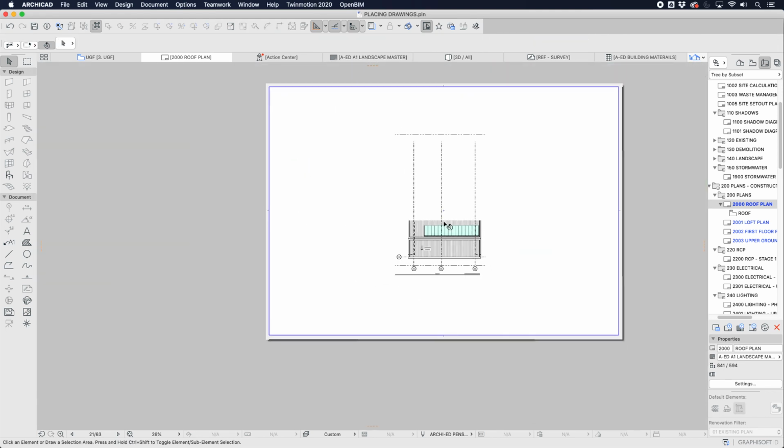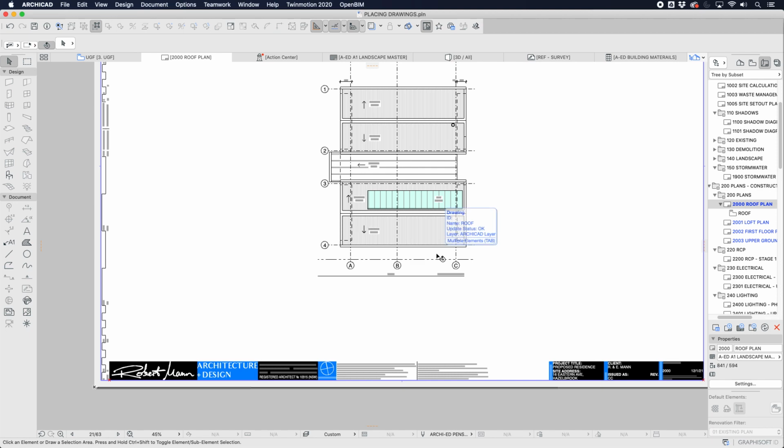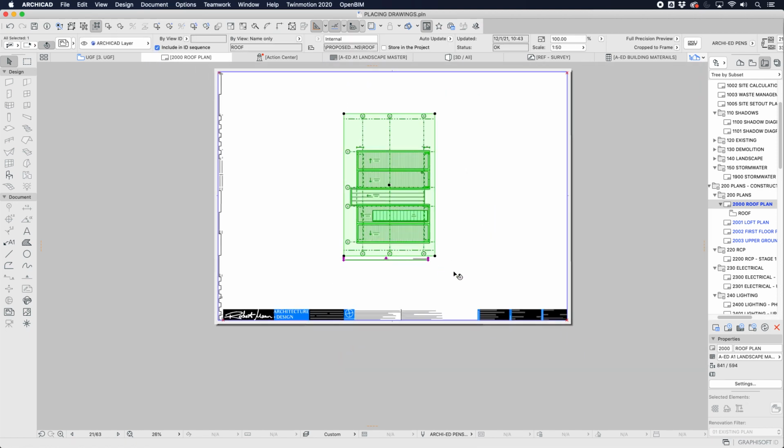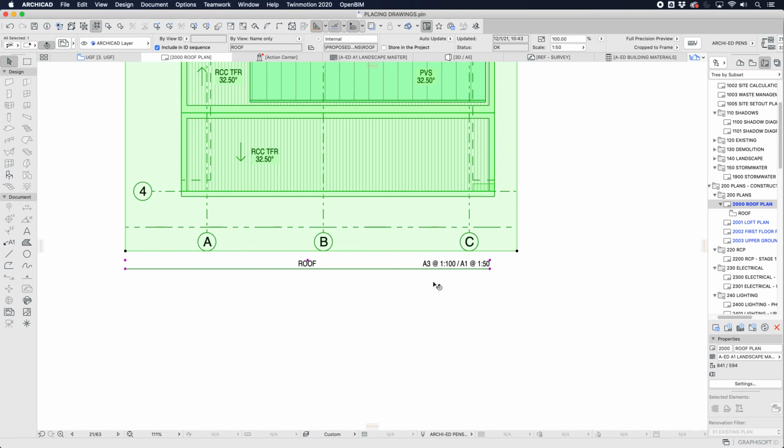and then we'll just give it a bit of space, just so it's not squished. All right, now you might say, do I need a drawing title? No, you don't. I like drawing titles because it is the best way in ArchiCAD to be able to both describe the name of this drawing and also to give the scale of this drawing.